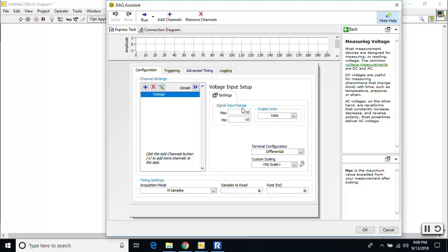And I'm not going to give you the answer here, but just remember the part that depending on our input resolution, we divide that range into a certain number of increments. So the better resolution, the better accuracy, to get that, we want to have a range that isn't far beyond what we're going to measure.